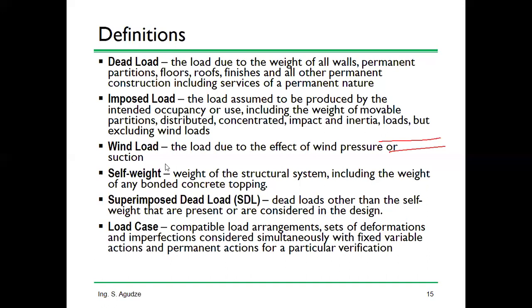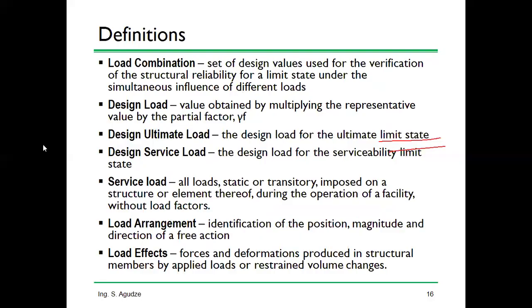Okay. Now, we have another one we call load combination. Here, what we are saying is that we have various load cases, but is it true that all the time, if let's say we have a dead load, imposed load, wind load, will all the three be happening at the same time? The answer is no. Sometimes the three will be together. Another time, only one will be active.